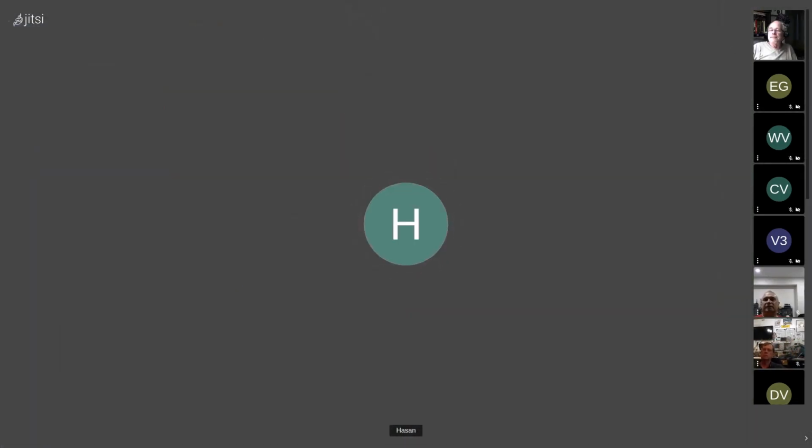Did I see a Sands hand up? Yeah, I was going to mention the same thing Dave was doing. There is another circuit you can buy as a kit. It's just an op amp with a pass transistor, and it also has current limiting. But the benefit is it's got a light that comes on, so it gives you some indication that it's in an overcurrent position. And you can adjust it slowly.